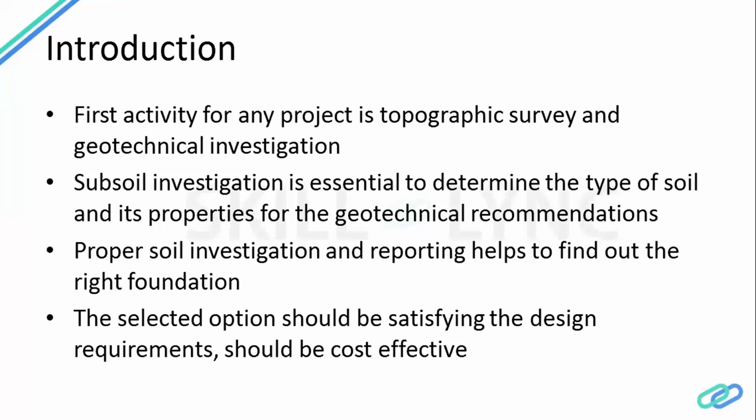There should be a certified engineer at site who will be supervising the investigation and ensuring that it's done as per the right practices. If the soil investigation goes wrong, then we will be working on the foundation system based upon that, so that's going to go wrong and later it may create problems. Based upon the soil report, we have to select the type of foundation that satisfies the structural requirements as well as being cost effective.